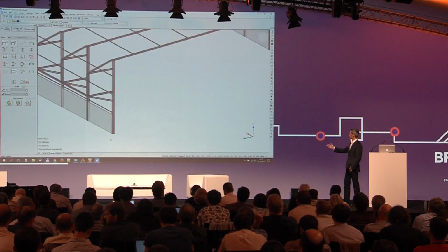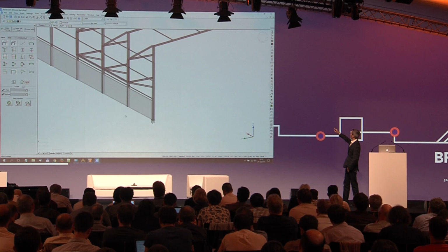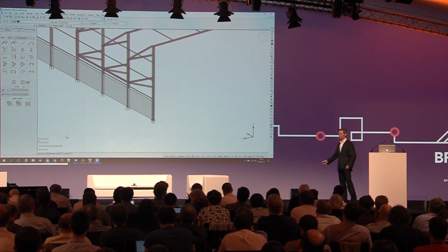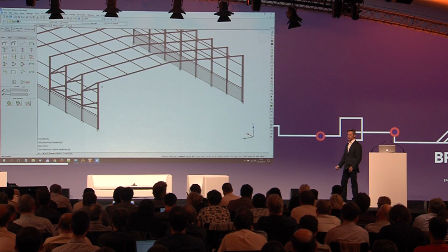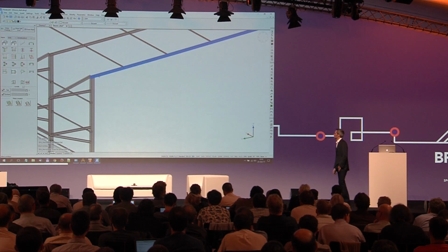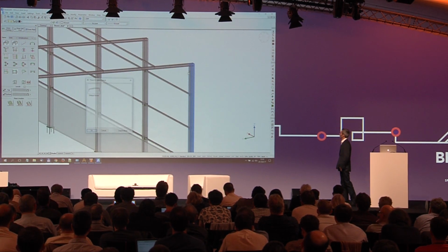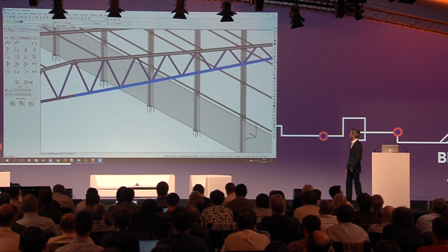So we'll also do this for base plates. It's the same thing. And after that, we will add some trusses as well, because the span of this building is too wide to support itself. We'll add some trusses for strength. This is also constrained in template drawings. So if we apply it here, it will adapt to this new size, this new location.